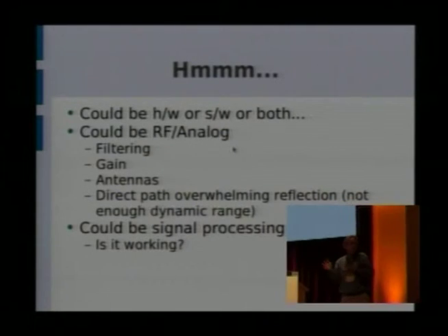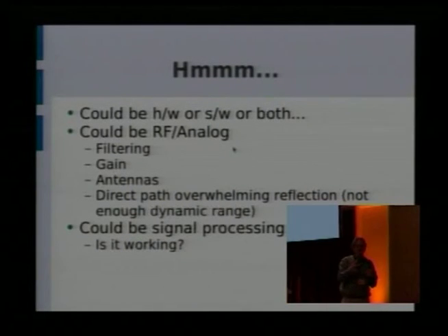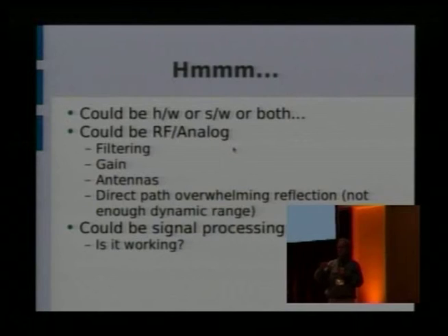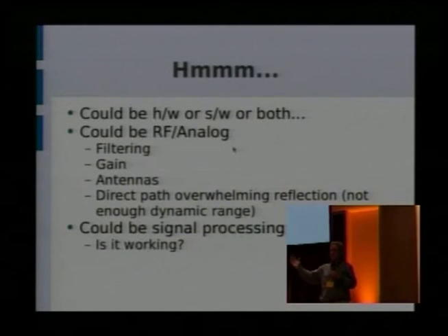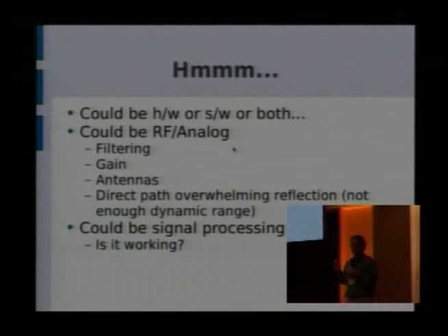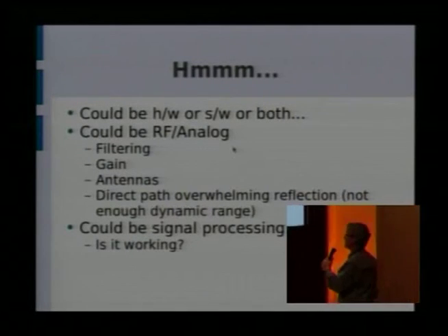It turns out for doing regular FM reception, it works, but part of the problem is that really, since everything is getting folded in here with no selectivity, you got all these potentially big signals on top of it. So it works okay for the big FM stations because they really still get bounced, but I think what's happening is that the small reflectance off the airplanes are getting swamped out.